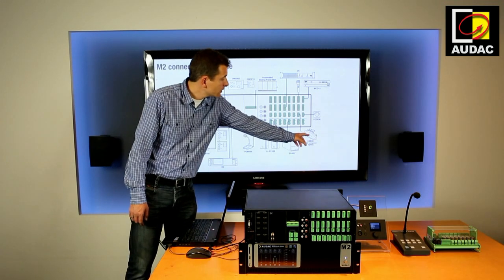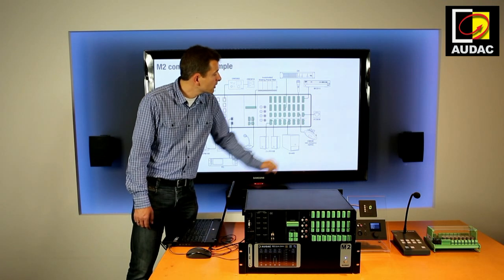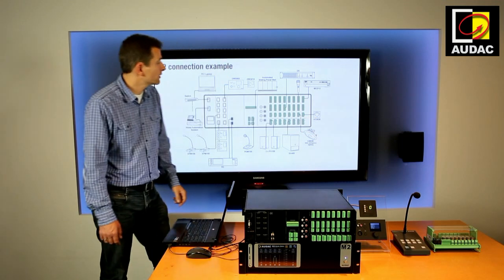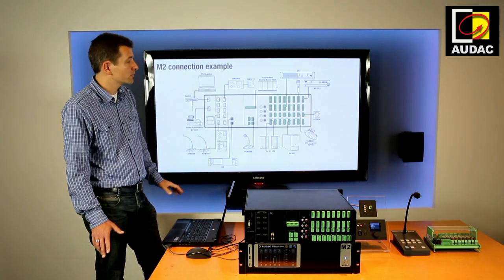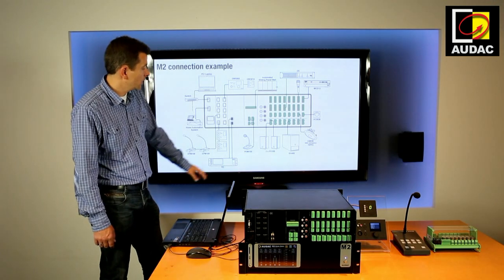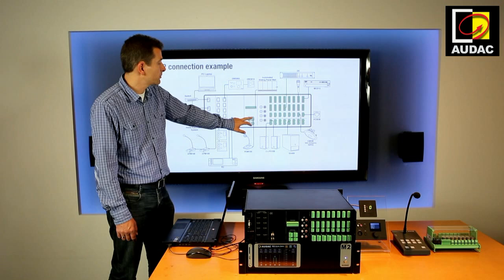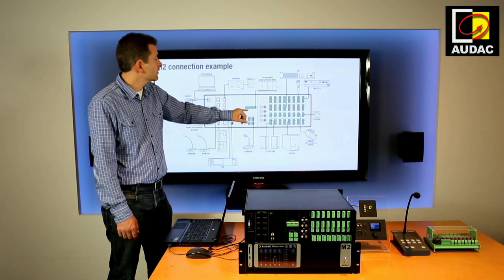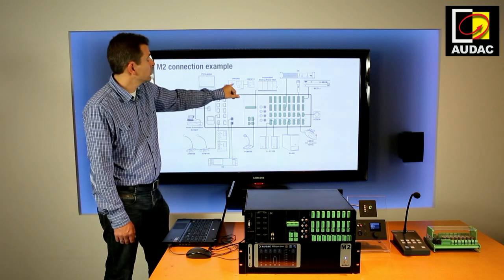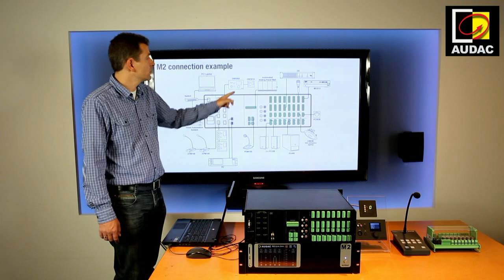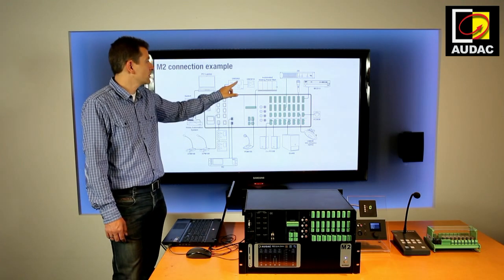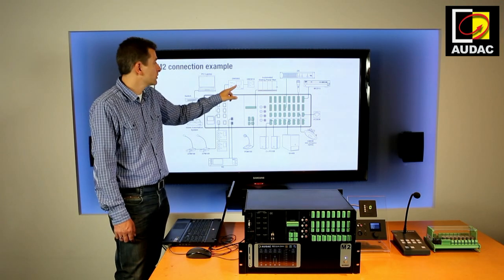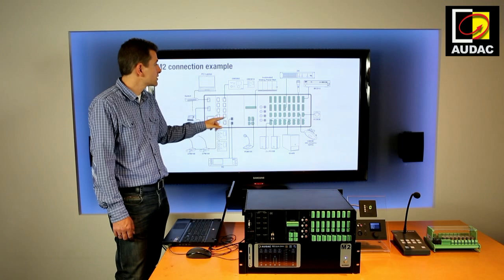We have a speaker with emergency lights on the relay output, and the relay output can also overrule the VC3036 100-volt volume controller. We have an emergency paging table on the priority inputs. We have a sliding wall on the contact input, wall panels over here. You can see you can only connect one DV5065 wall panel to each output. If you want to connect multiple, you must connect it to different outputs.